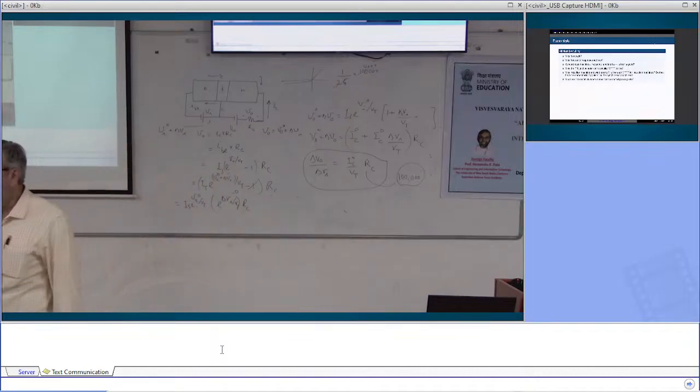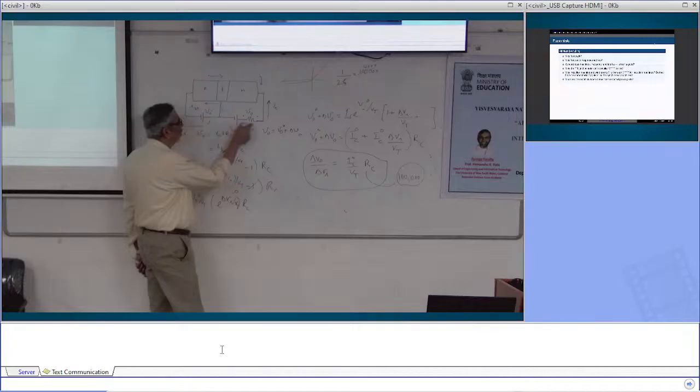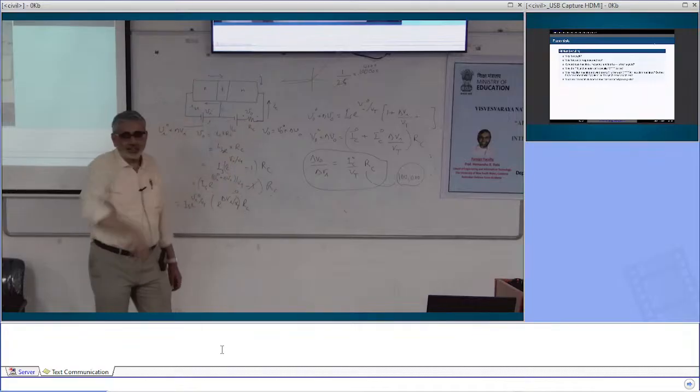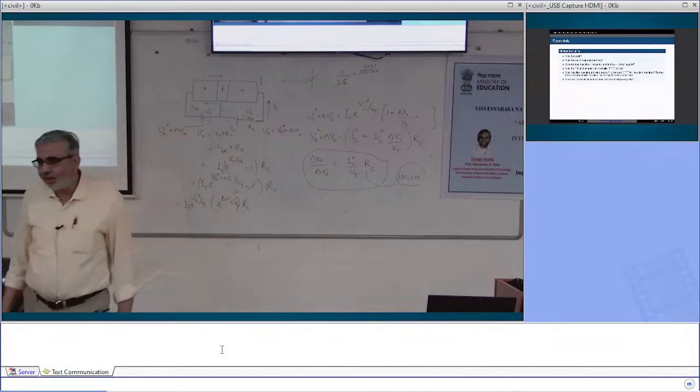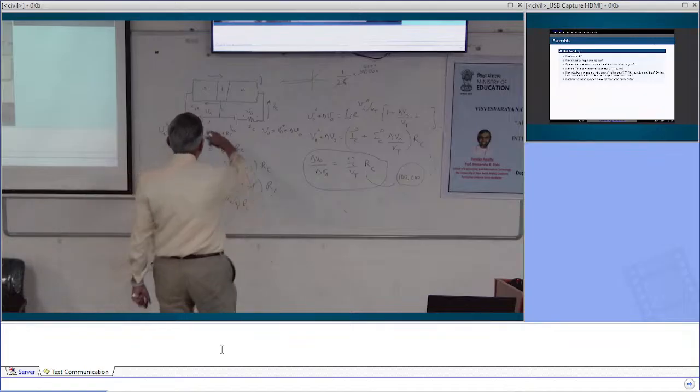That is a bit of an electronics matter. There are active resistors, which are transistors used as resistors. So it's available cheap. I mean, you can have 1 million transistors in a chip. So you can use that, and you can have very large resistances there. The only constraint is that this should not be larger than that, etc. So you just want high gain, you don't do that. So this is how the whole setup works.